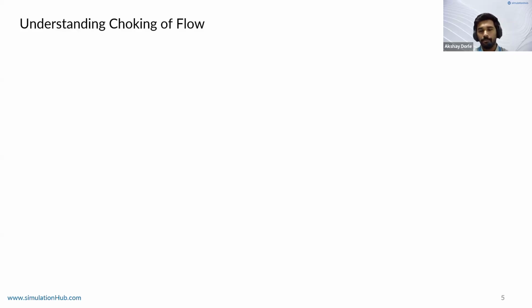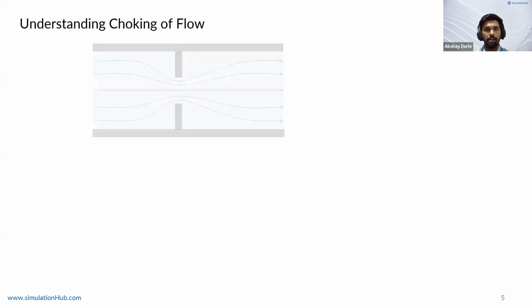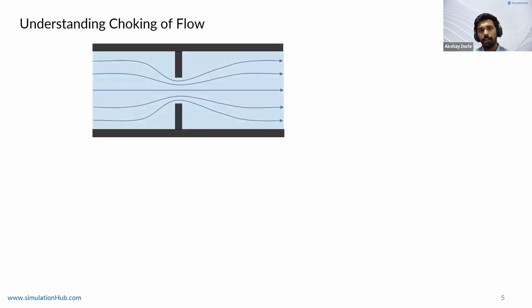Before jumping directly into the coefficient, the liquid pressure recovery factor, which is called FL, I would like to start by building the understanding of why FL is calculated and what leads us to FL. So let's start with a simple valve, which is an orifice plate, and assume an ideal flow.